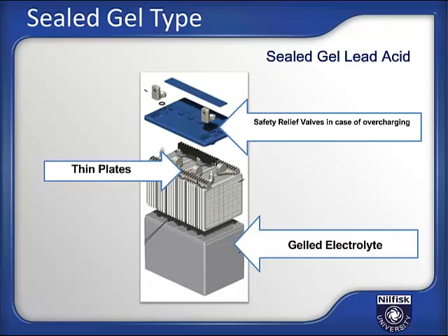So the major technological difference between gel and other deep cycle technologies is that gelled batteries or gel cells contain acid that's been gelled by the addition of silica gel. So basically what this does is turn the acid into a solid mass that looks like gooey jello. So compared to flooded lead acid batteries, there's many advantages of the VRLA category that gel cells fit into.